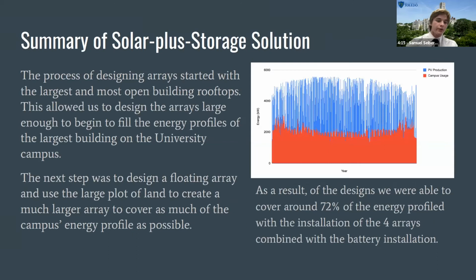The basic summary of our solar plus storage solution was we started with a couple of building tops, the largest building top arrays to cover the likely largest buildings that would swallow up the most power on the campus. And then we went to the floating array and the proposed ground solution. We were able to cover around 72% of the energy profiled with only 4 arrays and a combination with a